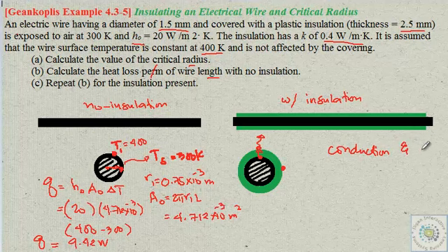Okay. So this will now be lumping those two processes. And conduction, in this case, will simply be conduction through a cylindrical shell, and it's easy to calculate Q for that, right? Q will just be equal to delta T, the difference in their temperature, over the